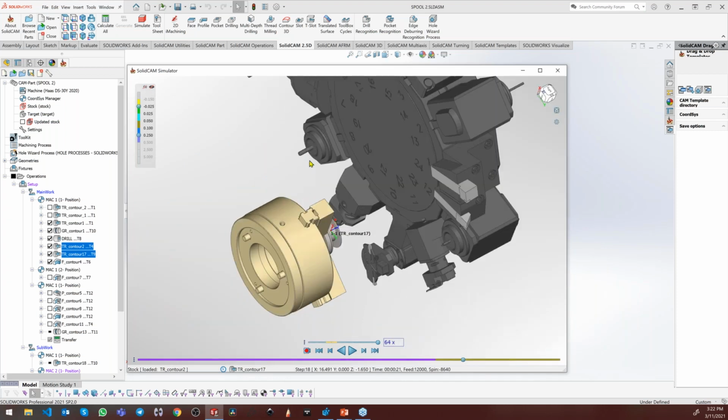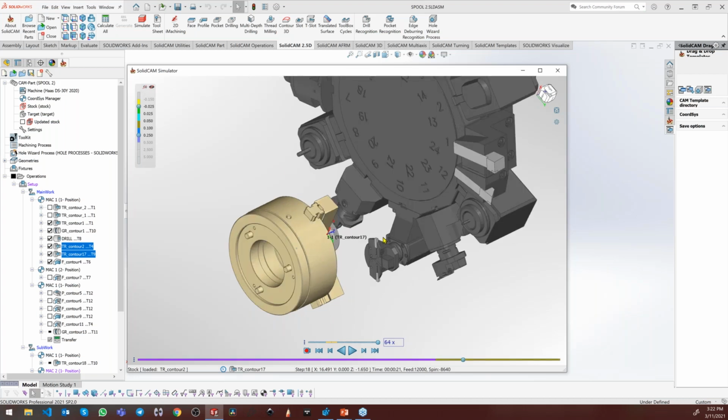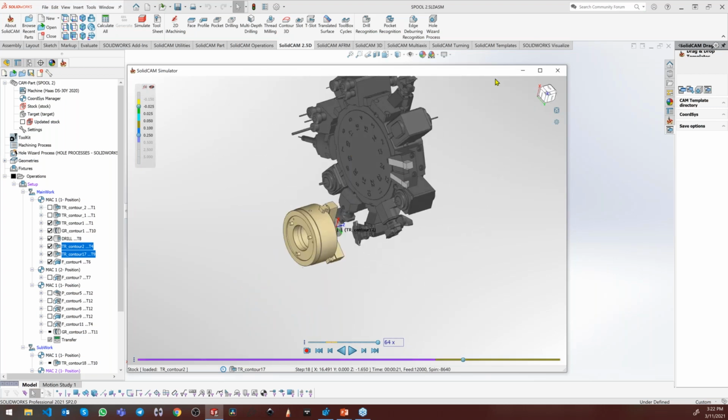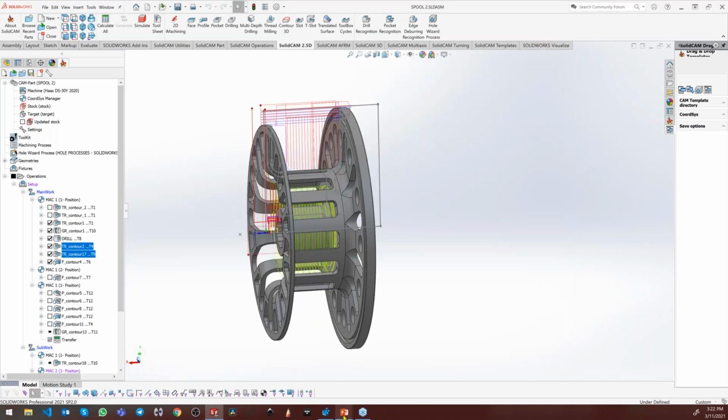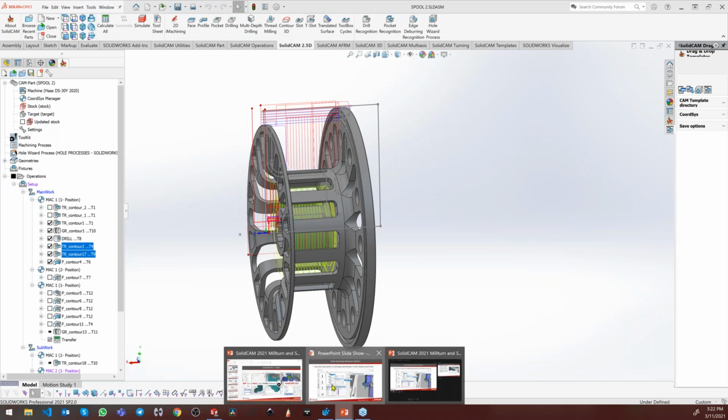I can do it even without going to machine simulation. So you see it loads very fast. You see huge models of cutters and inserts and fixtures, and the model itself appears in the simulation. It works very fast. It does not give you the kinematic solution of the simulation, but for first collision checking it is very powerful, and you can go to the tool table and by simply exchanging the stations get the perfect setup for your machine. I'll go back to the presentation.